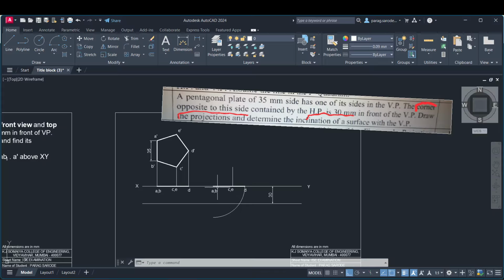Now I wanted to rotate this ABD or ABCED, keeping the AB as a center and the D point intersecting here. So how to do that? Select this line, select all annotations, right? But you can see that to select this, it takes time. So what I will do, I will move the mouse slightly upwards. I will click it here and you can see blue colored box is coming. Okay. Then I will select this line. In this way, all points which are required get selected.